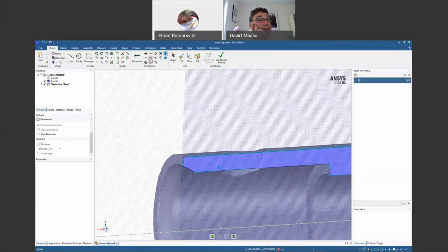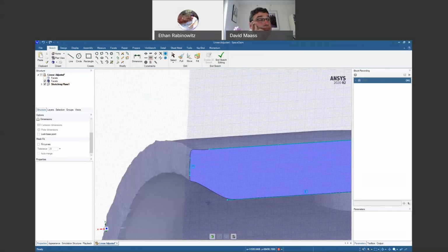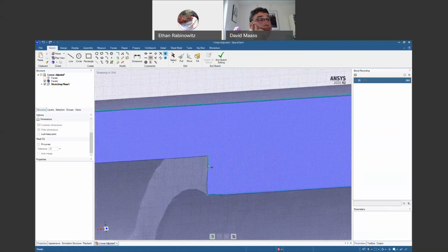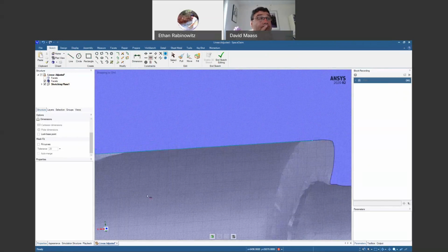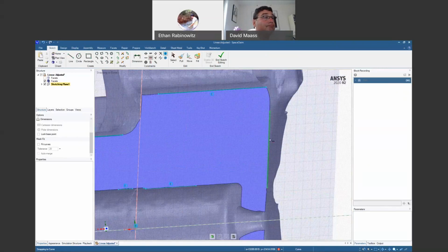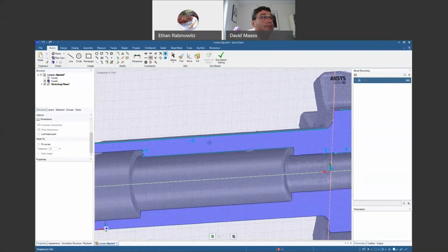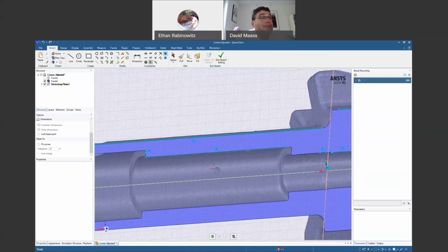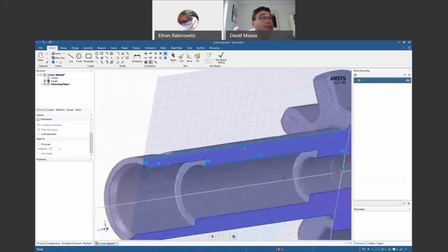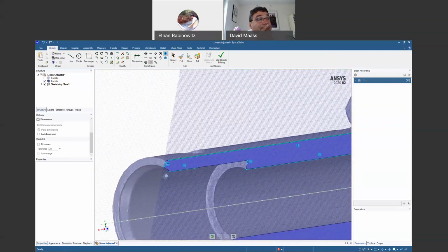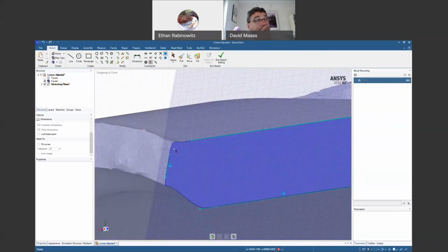So now we'll make the ones 90 to that horizontal. There. I could always zoom out. This one. All right, so I believe we've gone and, wait, did I do that one? There we go. Yeah, so right now, by default, these little icons don't show, but we have this nice little constraint tips button that just shows you which ones have been added. So we could have a nice little visual check. So those are good. And now the next easiest thing is to create my corners.